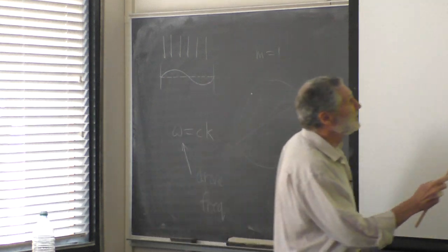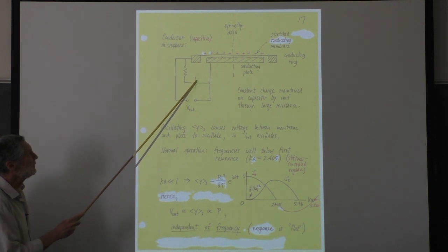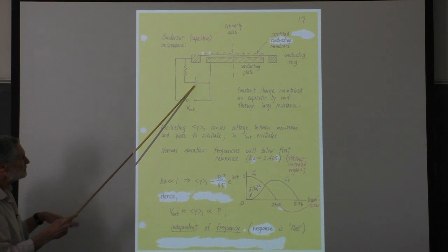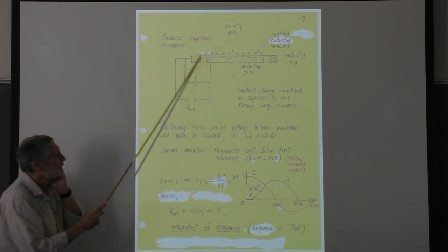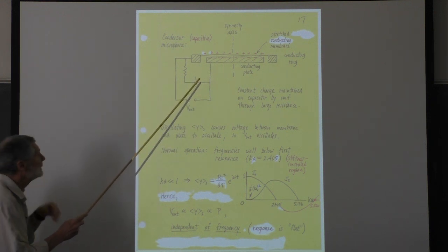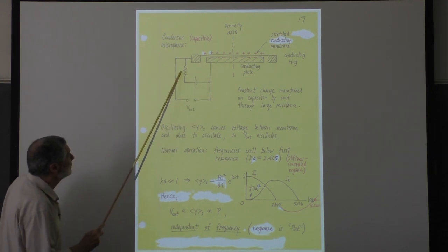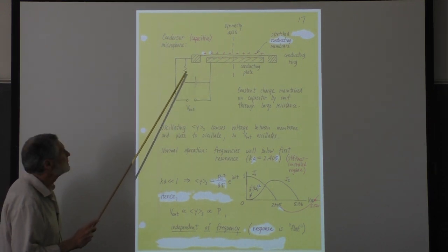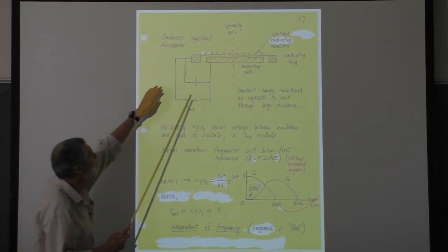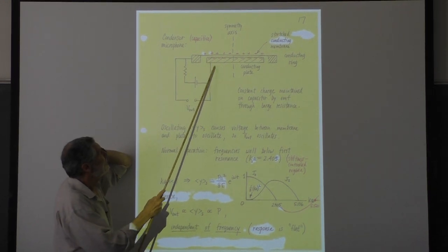So anyway, here we have to keep this at a constant charge. So what it's done is we have a DC voltage source here. It's typically 100 volts. All right, for this kind of capacitive microphone, it's not real high. It doesn't have to be real high. And we charge this up through a resistor. Okay, so, and assume we don't have the resistor first. Here's some voltage source. All right, so I've charged it up.